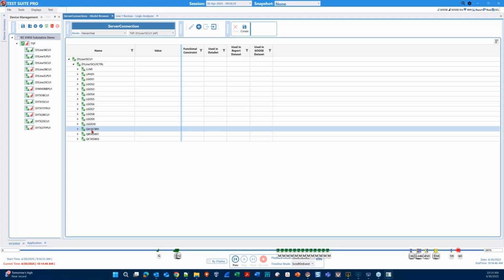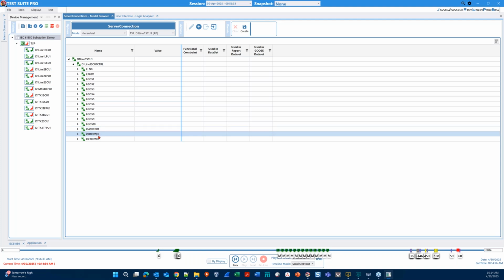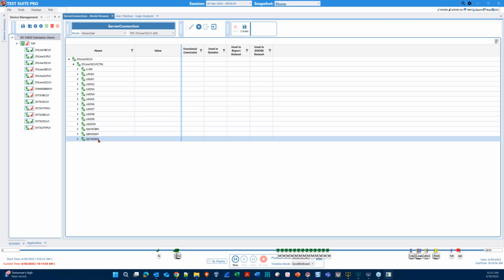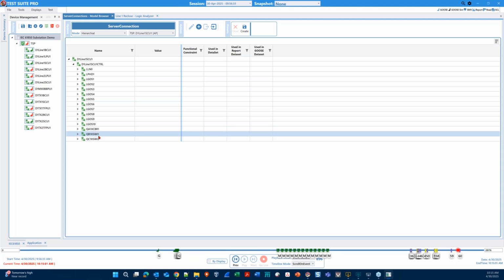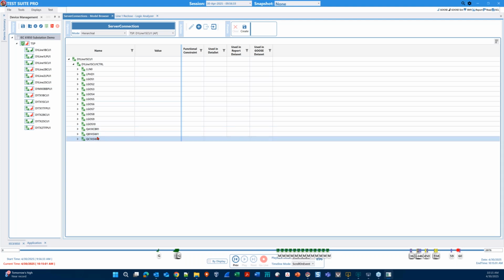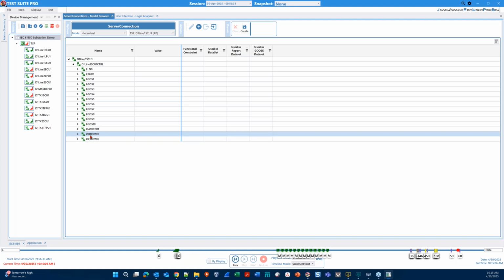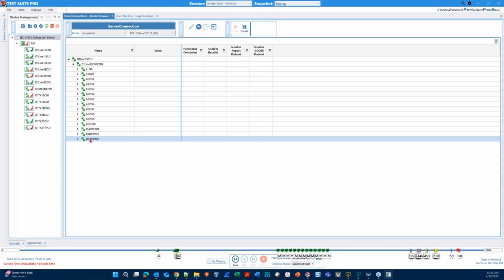In this context, QA1 references a particular breaker by name that we will have in our substation. XCBR is our interface to a specific circuit breaker, and the 1 at the end is just an instance number. You can see 1 and 2 down here for XSWI. These are interfaces to 2 different switches also in this bay, and they will have the names QB1 and QC1.